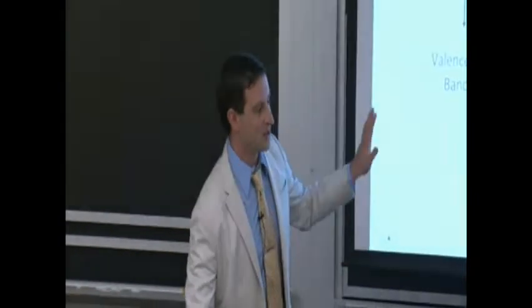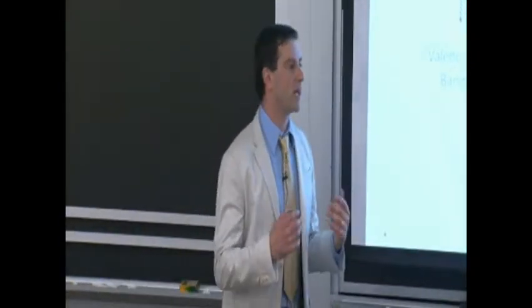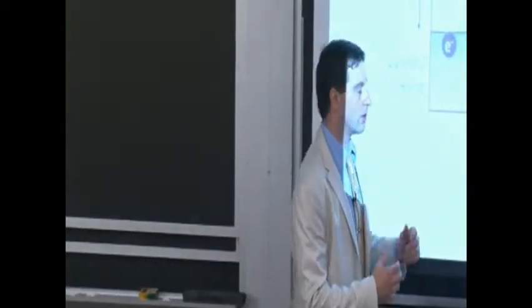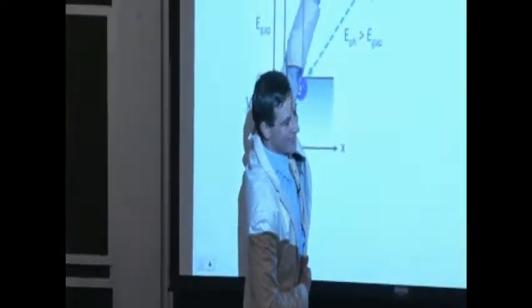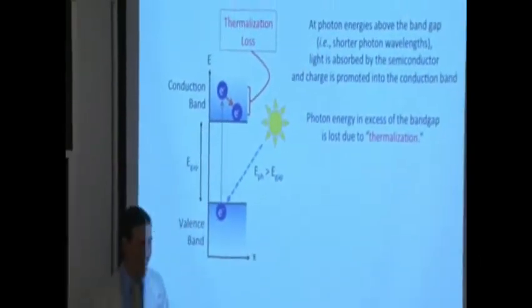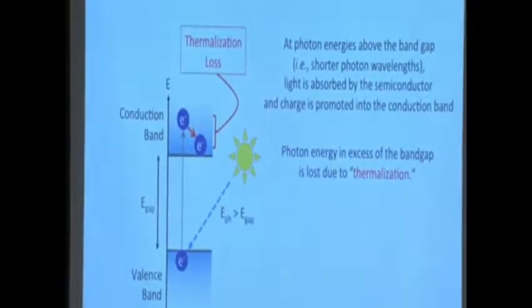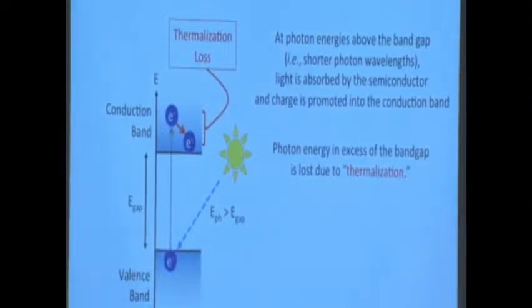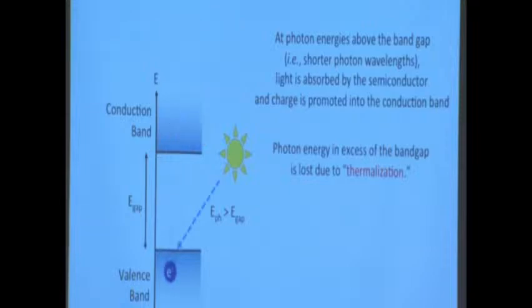It's not total loss, but from a mechanical engineering point of view, if you think about the thermodynamic efficiency of a Carnot engine, where your T high is this, and your T low is your ambient temperature, that delta there really doesn't look that good, right? Yeah, it's really tiny. So you have to think of a more clever mechanism, perhaps through a thermoelectric device or some other mechanism to extract that extra thermalization loss.